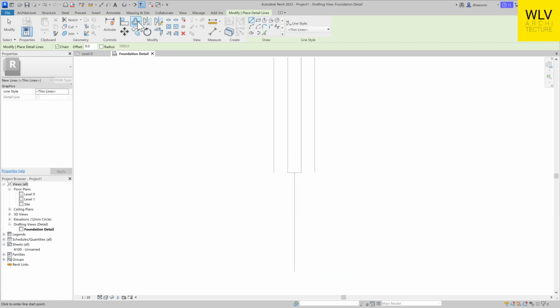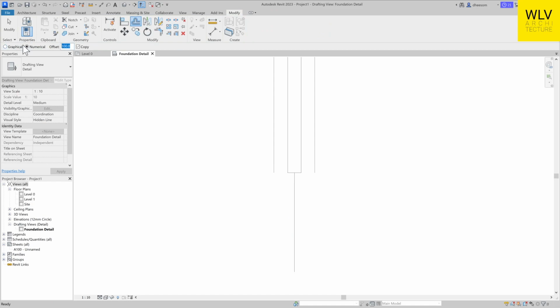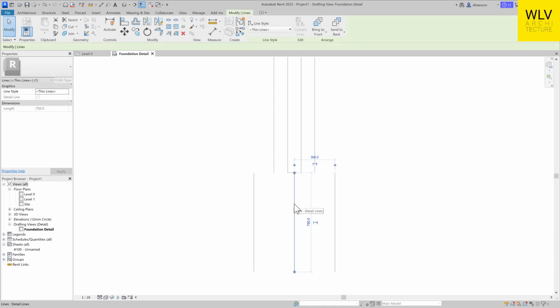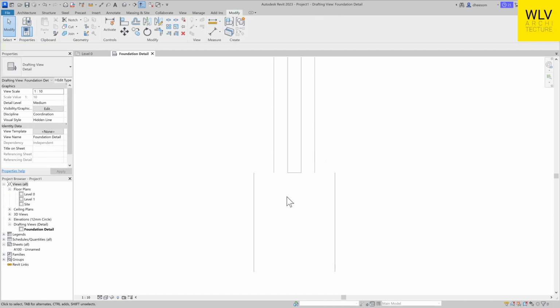down, and then I'll offset that 300 either side like that. So that's my 600 wide. I'll delete that line from there. And then there's another tool I can use here, which is the Trim Extender Corner. Really useful tool. We click that, we click that one, we click that, we click that, and it trims, or extends in this case, to the end point.